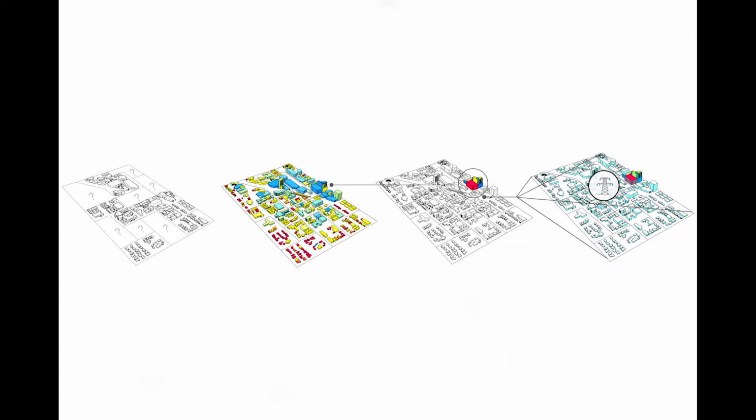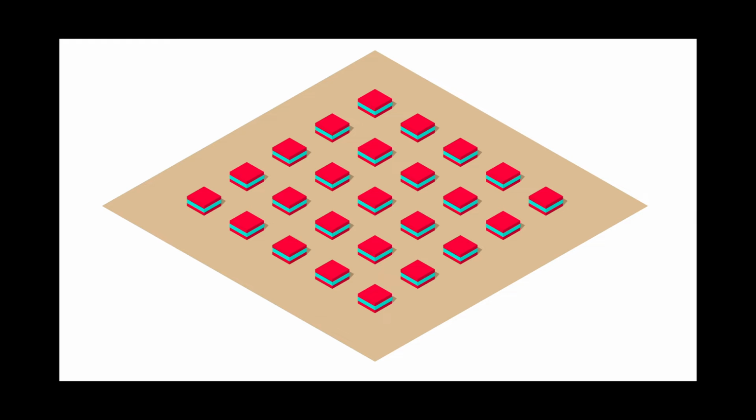The simulation depends on a building's volume, the number of floors that the building has, the structural material it is, and the proximity it has to other buildings. To start with the control, I used a building in Boston that has a floor height of 3 meters and an area of 36 meters squared, with all the window-to-wall ratios being 40%. The total operational energy ended up being 191 kilowatts per meter squared with wood construction.